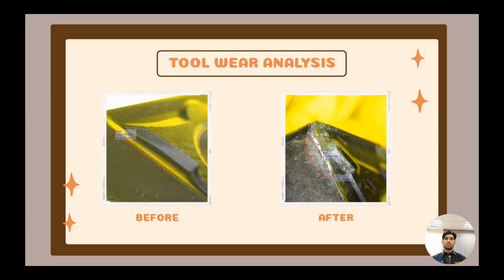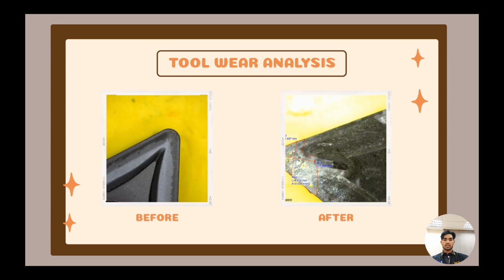The next picture shows the cutting tool after it has been used. According to the observation made, after using the point of the tool, it has left a mark, what is known as flank wear. The flank wear area is 1.375 square millimeters.